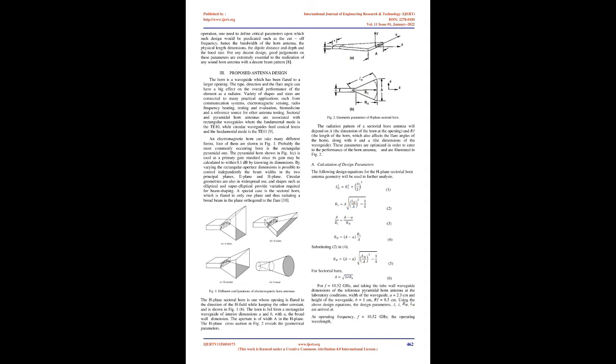Horn antennas can be designed in a variety of shapes and sizes to fulfill many practical applications and can be used as feed elements for other antennas such as reflectors. There are several factors that influence the on-axis gain of horns. When calculating the gain, it is usually assumed that only the dominant mode TE10 is present and propagating within the antenna. However, this does not occur, because when the dimensions of the antenna become larger, other higher modes will appear in the antenna aperture, changing its gain.